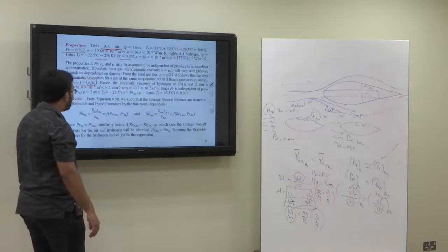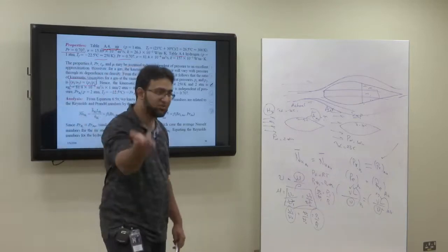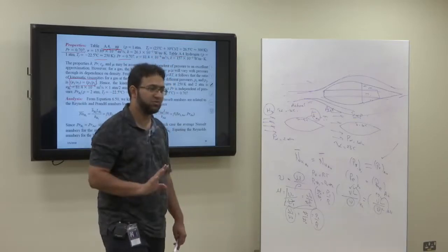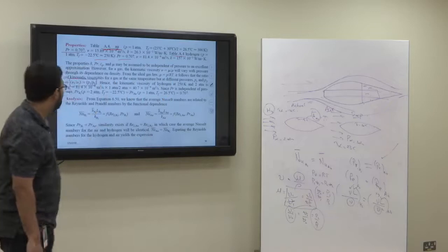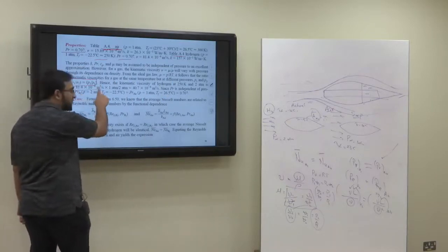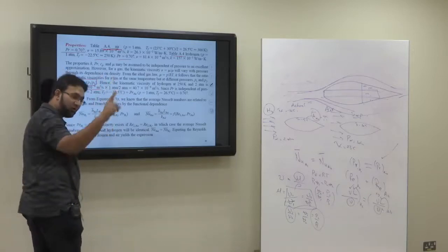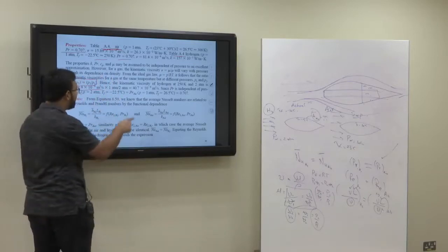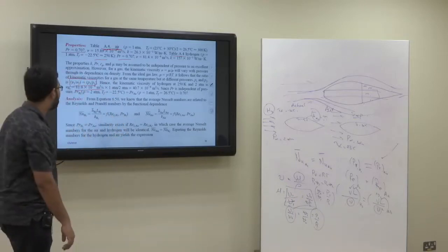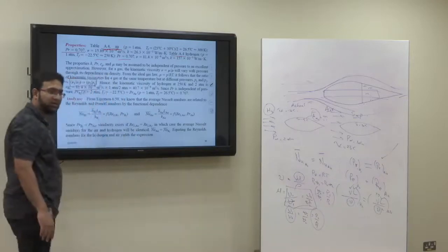So now if we know viscosity at one condition and the pressure at that condition, we can find what the viscosity will be if we change the pressure. So we determine the new viscosity, and it will be the viscosity that you get from the table multiplied by the pressure over which the table is given, divided by the pressure over which you are trying to find it. So it's actually divided by 2 in reality.